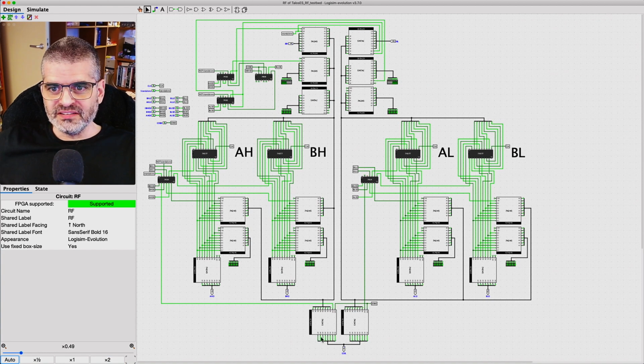So this is it. This is looking good. The functionality is what I wanted it to have. It's working both in in-system mode and standalone mode. It's driving all the lines correctly. There are no bus conflicts. This internal logic here prevents some of the bus conflicts. Other bus conflicts are prevented just in the way I encoded the instructions. So I'm happy with it. So let's now transfer this to schematics that we can use to design a PCB.